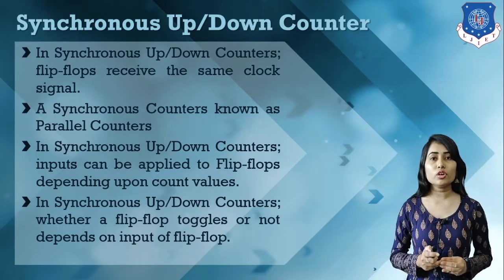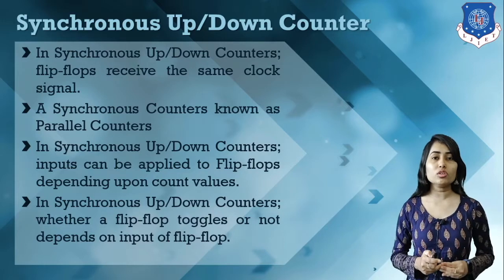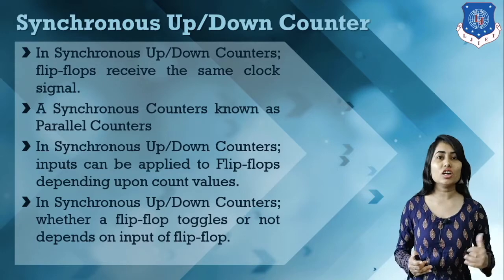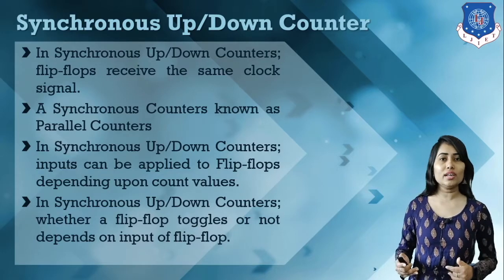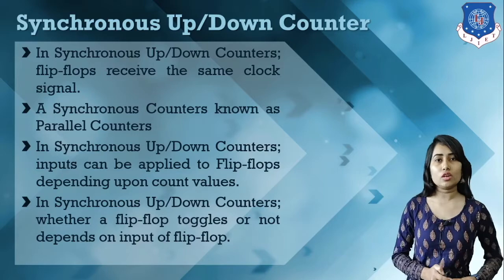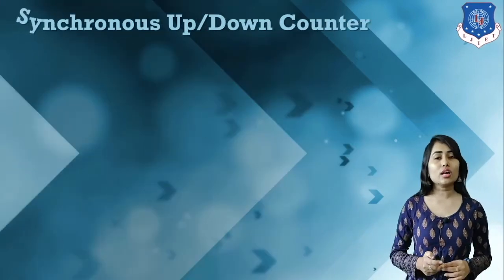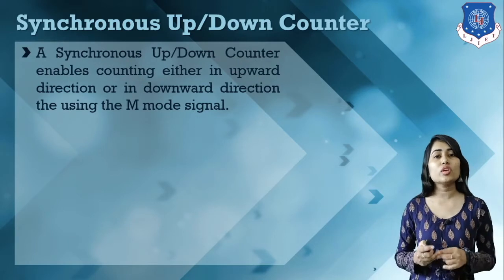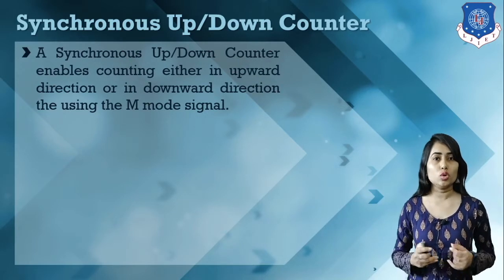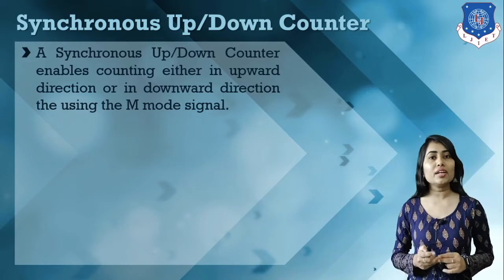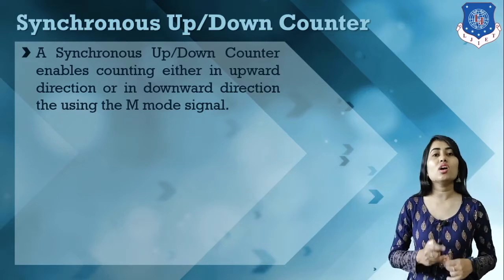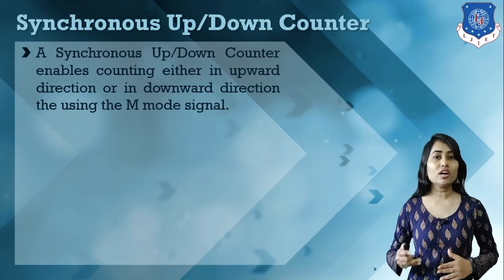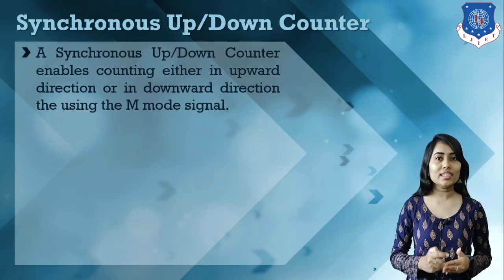Now, whenever we want to design this synchronous up and down counter, we have to design a counter which counts either in an upward direction or in a downward direction depending on our requirement. To count in either direction, we have to use one mode signal, that is M.